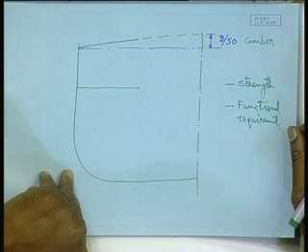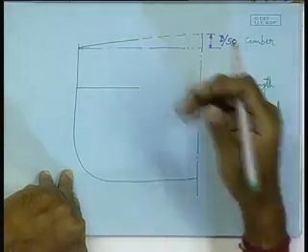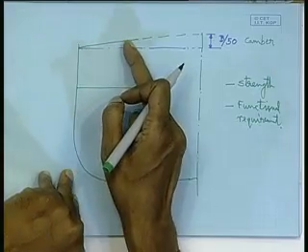for the entire shape. Once that is done, then you start with the midship section drawing. Physically you lay out and draw it. Well, if you do not draw it, there is not a problem, provided you have calculated all the structural items that are going to come in the midship section, and you calculate the section modulus. But it is worthwhile to draw, because that will be needed for approval by the classification society.